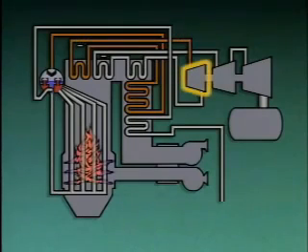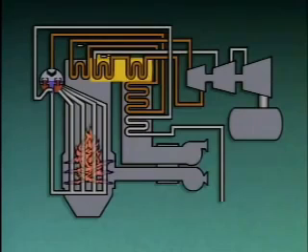As the steam flows through the HP section, it gives up a lot of its energy and its temperature and pressure drop. Before it moves on to the other sections of the turbine, the steam returns to the boiler where its temperature is increased as it flows through one or more reheaters. Reheaters are very similar to superheaters. They use heat from the boiler furnace or from hot combustion gases to raise the temperature of the steam.